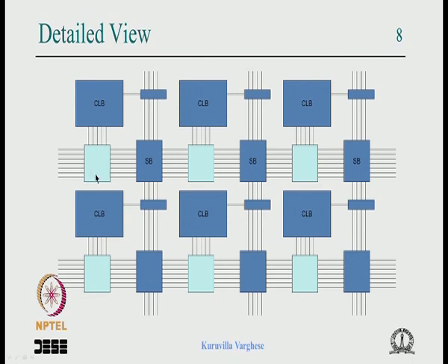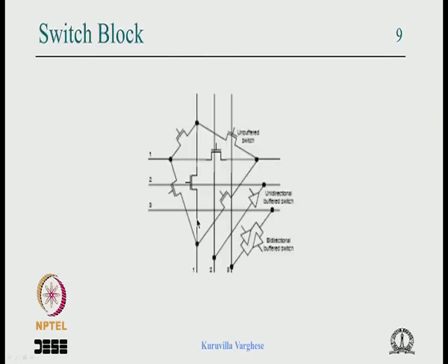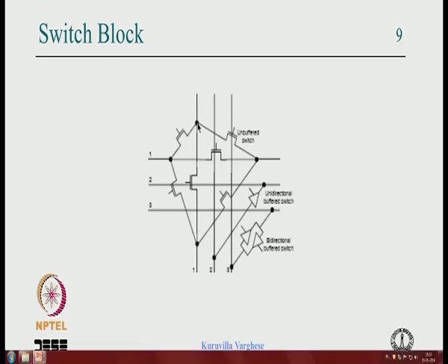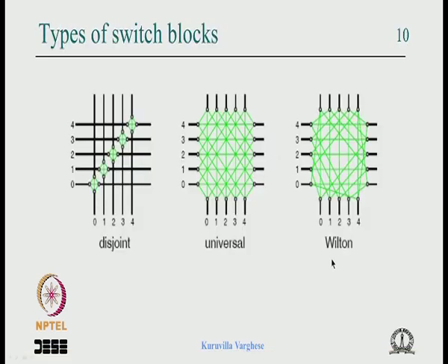So there is a lot of programmability, and this is called a configurable logic block because the logic block itself is quite big. We will discuss why it is big. So it needs a lot of configuration. This also shows a switch diagram, where a horizontal wire and a vertical wire are connected. At least one wire is connected to left, right and bottom, and this shows various types of connection, depending on the statistics which each vendor uses.